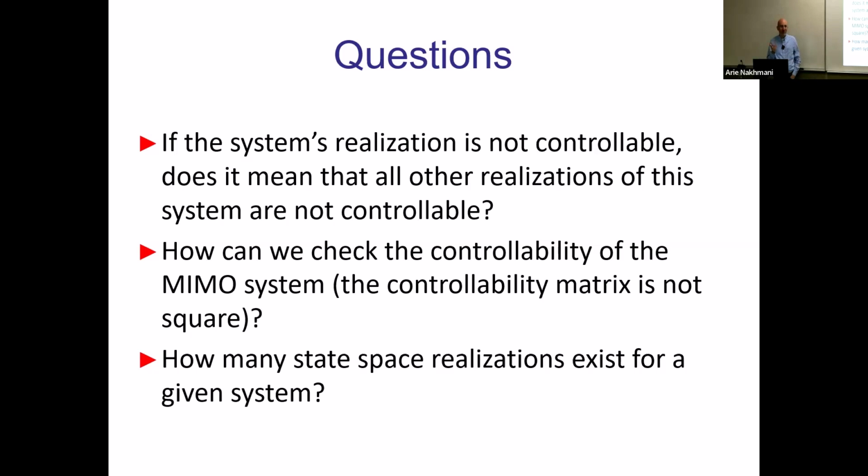Not all definitions of the state will be non-observable. But if you require observability, which means you cannot measure any of the states, you can measure only output and input, and you need to compute all of the x's, you will lose some of the controllability properties. You cannot have both if you have cancellation between zeros and poles, right? So this might be a problem for some designs.